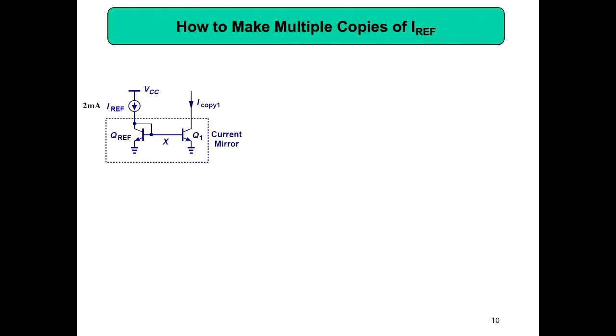Then, so we have got 2 milliamps. So that is the golden current. This current is coming from the band gap reference that you have connected to this transistor topology so that you can get a copy of this golden current. So if this is 2 milliamps and if we neglect this current, your 2 milliamps is coming down to this point. From this point the current is actually branching into 2.